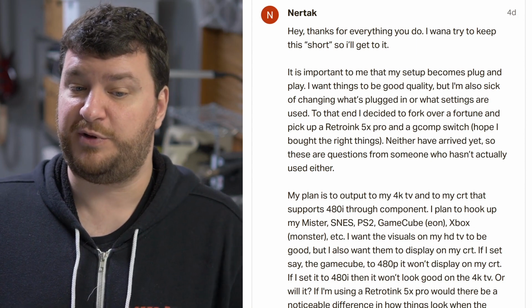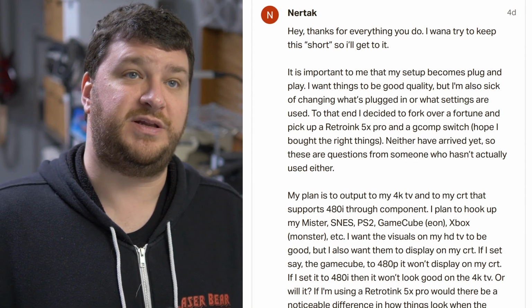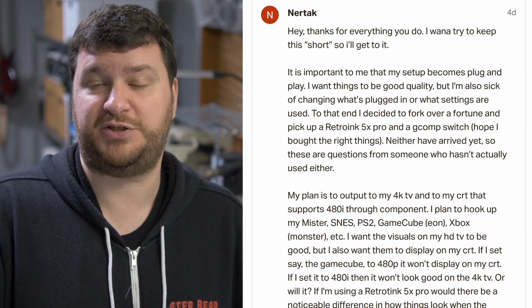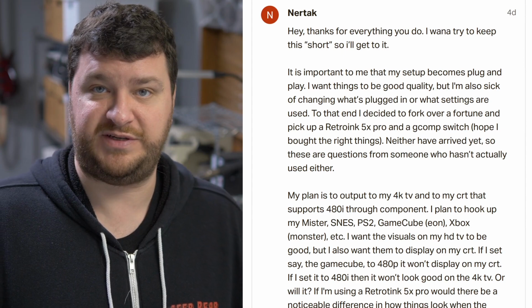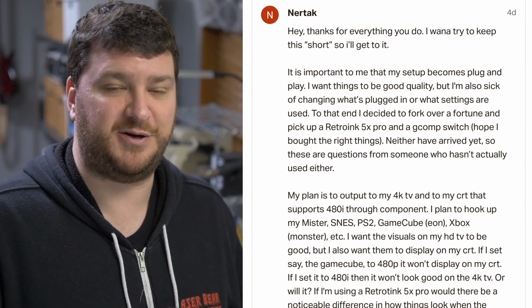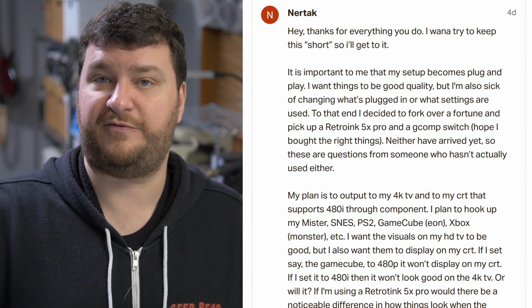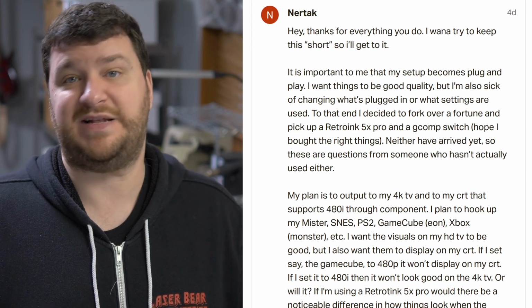You said you want everything plug and play, so you would probably need to take that second component video out and put it into another powered component switch or distribution amp or something, and get that between your consumer TV and the component to VGA converter for the VGA monitor. And once again, you'd want to turn off whichever monitor you aren't using. That's going to add some cost.